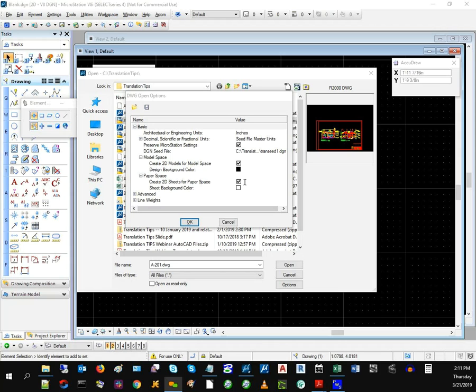then if you don't set up the units in this options area correctly, you're going to get a small discrepancy. And I hear this all the time. I open the DWG files for my civil project, and things aren't in the right location. I've got to scale them. I've got to do all sorts of things to get them to look right. So if you're bumping into that, it's because you don't have your options set correctly here.